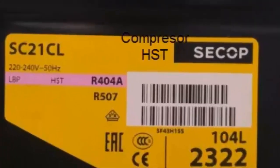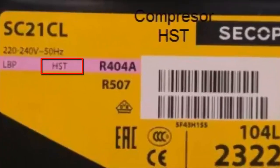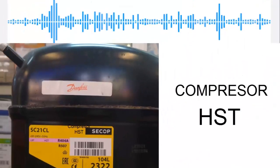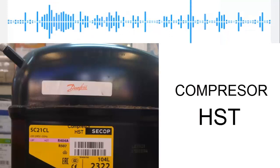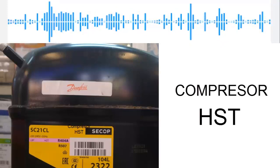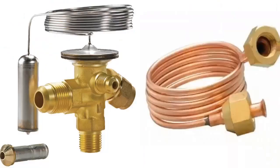What does HST mean in a refrigeration compressor? Let's start by saying that the acronym HST in a compressor means that its motor has a high starting torque. Compressors with high starting torque are those that can use either a capillary tube or a thermostatic expansion valve as an expansion element without any issue.